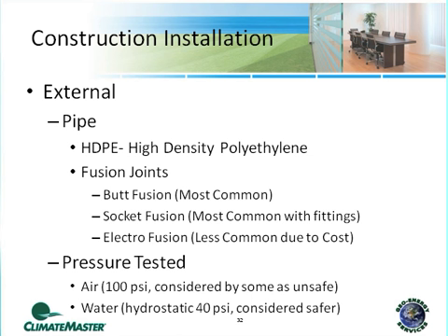We actually heat that pipe up to its melting point and push it together in a butt fusion process, which is the most common one, all right? And once that pipe cools down, that joint actually becomes stronger than the pipe itself. There are also electrofusion joints and socket fusion joints, which are the other common ones that you'll see out there in the field.